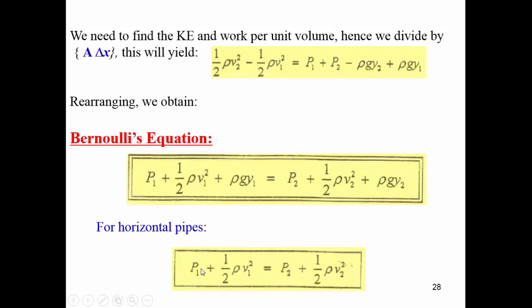Now notice in this equation that the velocity and the pressure are related to each other, meaning if in region 2 the velocity increases, the pressure has to decrease in order to maintain the equality. And the same thing, if the pressure happens to decrease, the velocity has to increase to keep the equality. This has very important implications, especially in airplanes, science, and aviation.